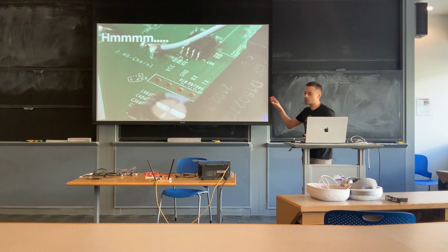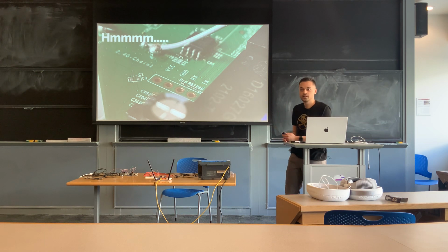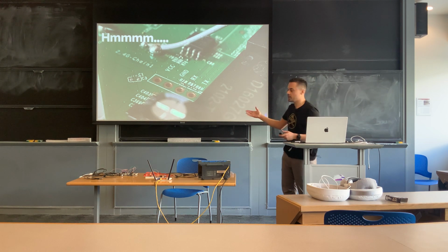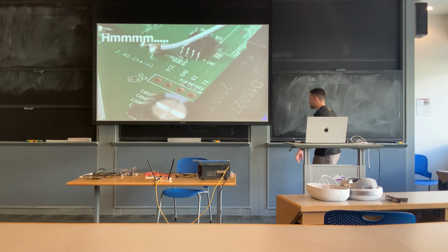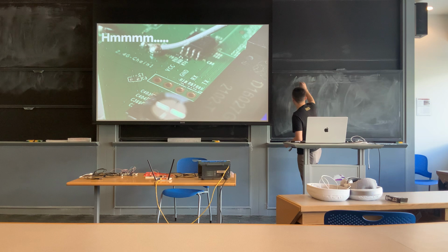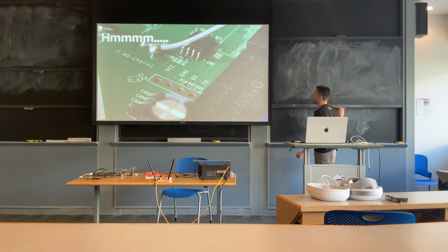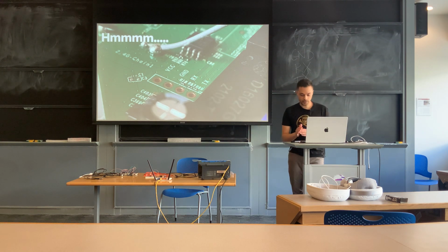It looks like these were put here intentionally by the designers as a breakout board for someone to be able to attach to. So I'm actually going to go ahead and write those down here, so we'll see these come back in a minute. We have VCC, ground. I'm guessing that's what GND means. It could not mean that, but we're going to take an assumption here. We have RX and TX. Go ahead and lift that up so everyone can see. So those are our 4 pins here.